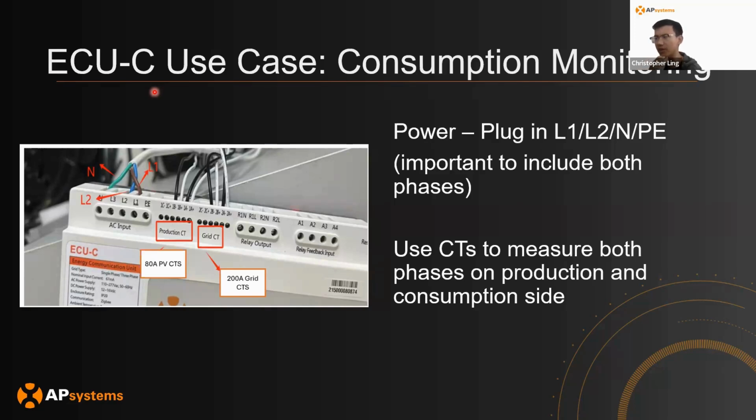For lower wattage panels, the challenge I usually see is that the VMP is pretty low, much lower than 28 volts. If that's the case, those won't work with our microinverters. But if that older panel does have a VMP between 28 and 45, then it will be able to work.